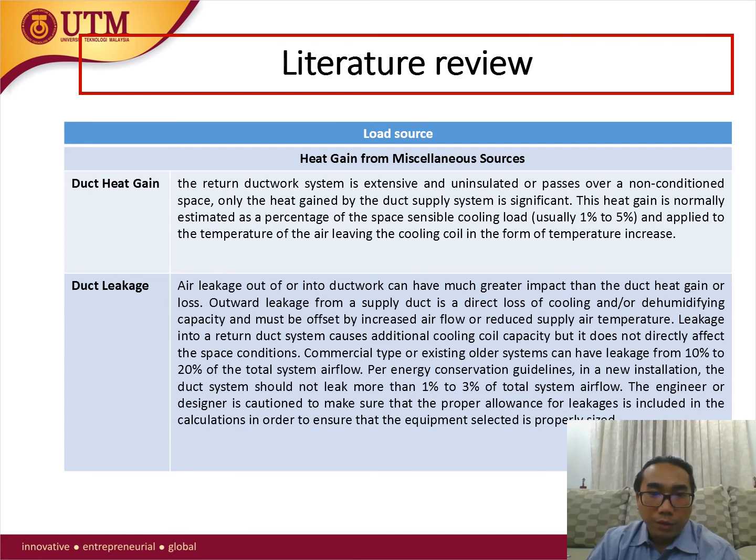Per energy conservation guidelines, in a new installation, the duct system should not leak more than 1% to 3% of total system airflow. The engineer or designer is cautioned to make sure that the proper allowance for leakage is included in the calculation in order to ensure that the equipment selected is properly sized.